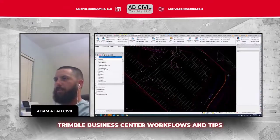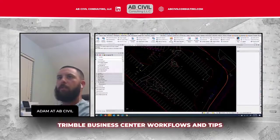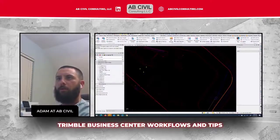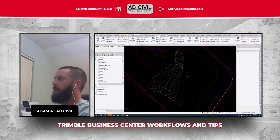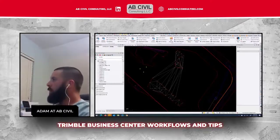So now basically I've created 3 boundaries that are around the outside of all 3 of these surfaces. So all I'm going to do now is turn those 3 surfaces off, and go back to the cut fill surface, which has all these triangles connecting it because I added each of the undercut surfaces as members to this one cut fill surface.